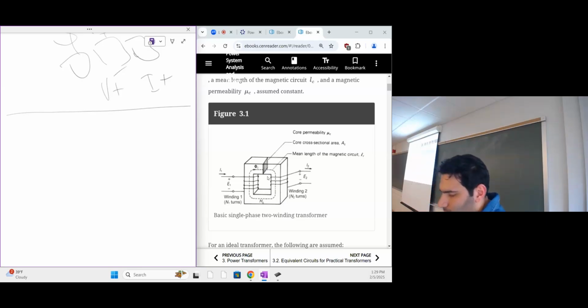So let's say if I tell you the cross-sectional area is 4, and it's a squared shape, so that means each side is 2. So this is 2 here. And then you know that this line here is at 0.5, okay? So if this inner square is 8, the length of this will be 10. And then LC will be 40 because this dotted line should be a square. Okay? Normally, I will not ask you such questions, but in case you need to do some calculations, you need to figure out those values. Other things related to the magnetic materials will be given for calculations.